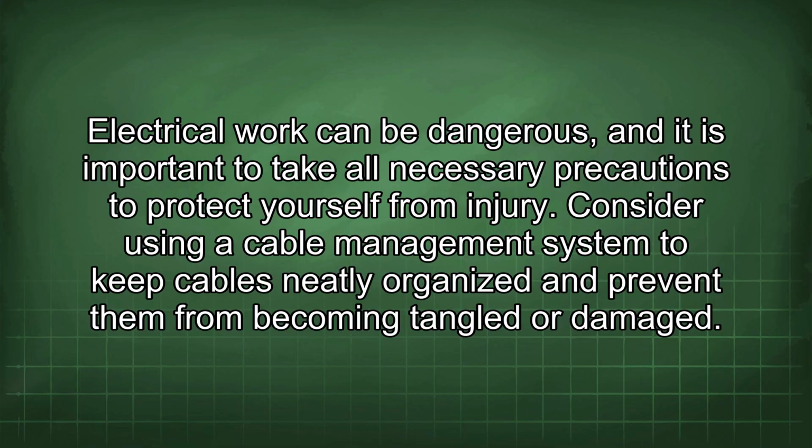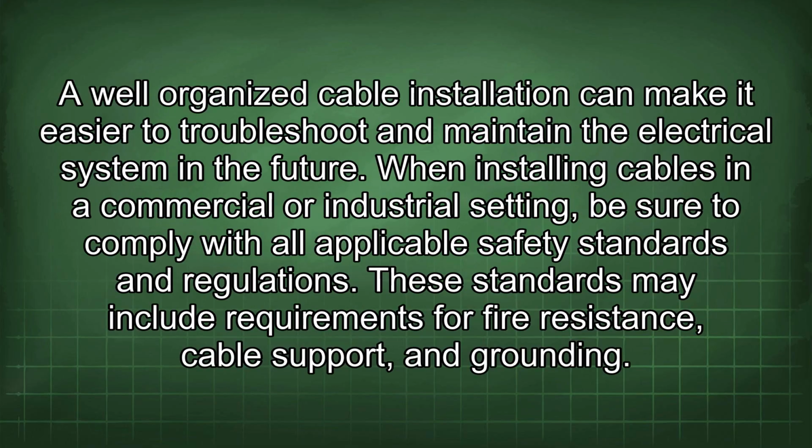Consider using a cable management system to keep cables neatly organized and prevent them from becoming tangled or damaged. A well-organized cable installation can make it easier to troubleshoot and maintain the electrical system in the future. When installing cables in a commercial or industrial setting, be sure to comply with all applicable safety standards and regulations. These standards may include requirements for fire resistance, cable support, and grounding.